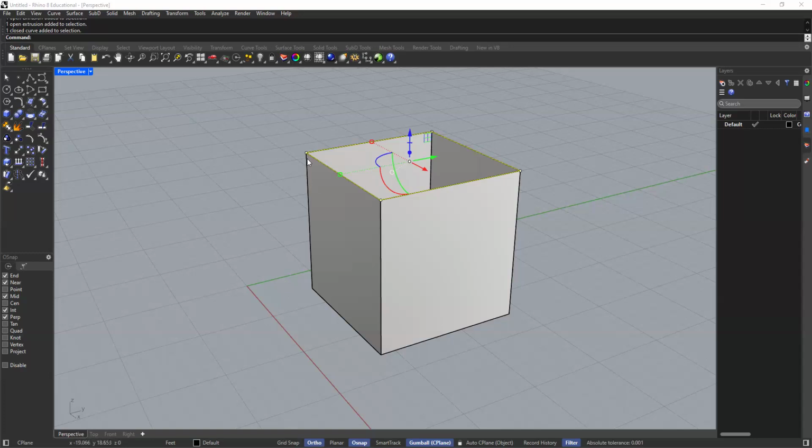And now I have the line work. I have this line work so that I can create a surface between all of the line work. In order to create a surface from lines, I'm going to come over here to the surface creation tool, which is this one right here. It's a rectangle with 4 dots, but it has a pull down, a little triangle on the bottom corner. I'm going to click on that triangle.